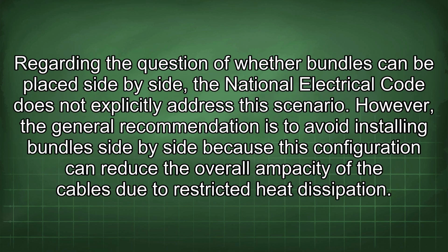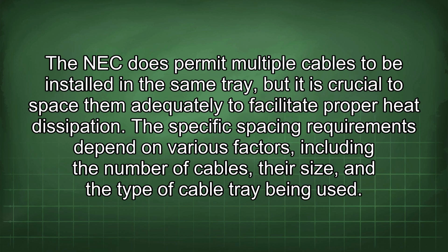Regarding the question of whether bundles can be placed side by side, the National Electrical Code does not explicitly address this scenario. However, the general recommendation is to avoid installing bundles side by side because this configuration can reduce the overall ampacity of the cables due to restricted heat dissipation. The NEC does permit multiple cables to be installed in the same tray, but it is crucial to space them adequately to facilitate proper heat dissipation.